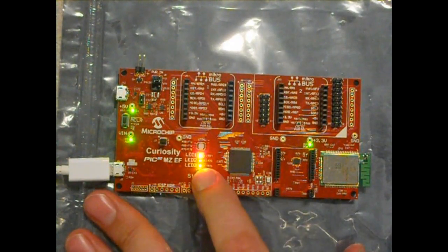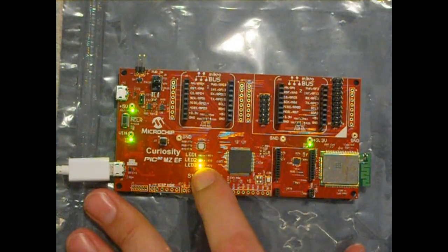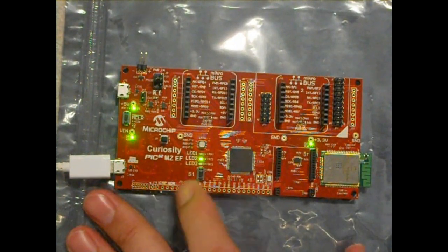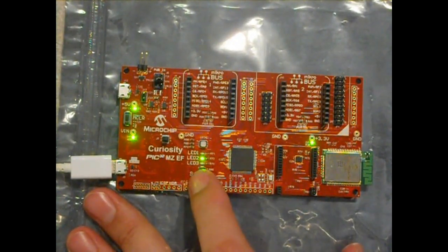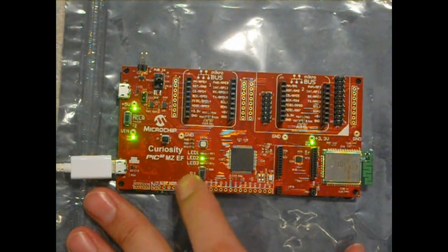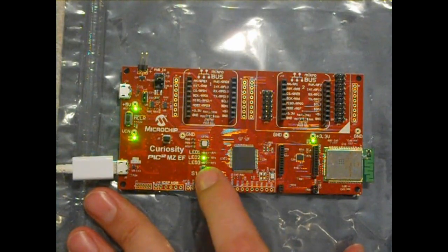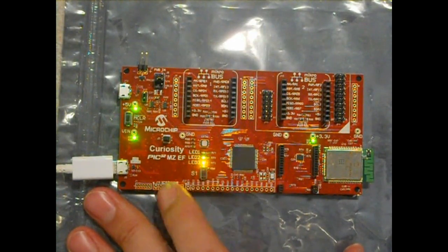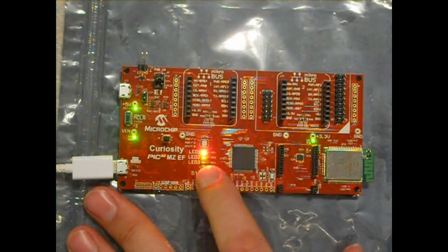So for example, there it was fast and responsive, there it didn't respond at all. So you can actually hear that I'm pushing the button several times with no result. And really the reason for that is that you have to keep the button pressed down while the code is running over the line that's checking to see if the button is depressed. So if you hold it down long enough, it will always illuminate. And you can actually see if you hold it down forever, it'll flash, essentially.